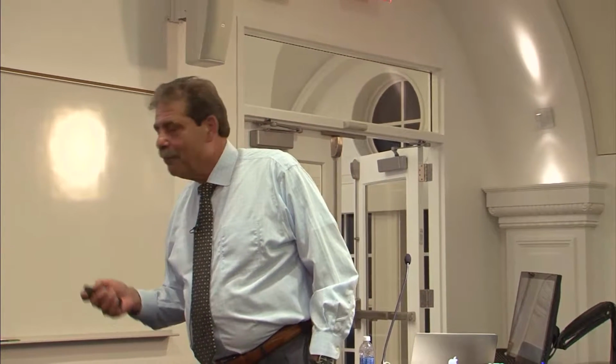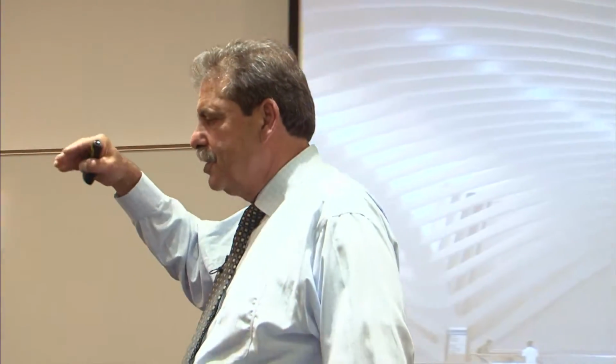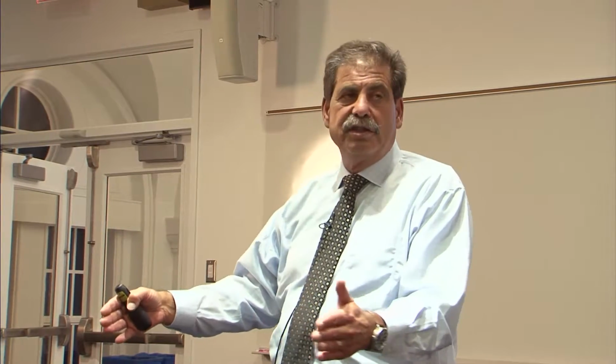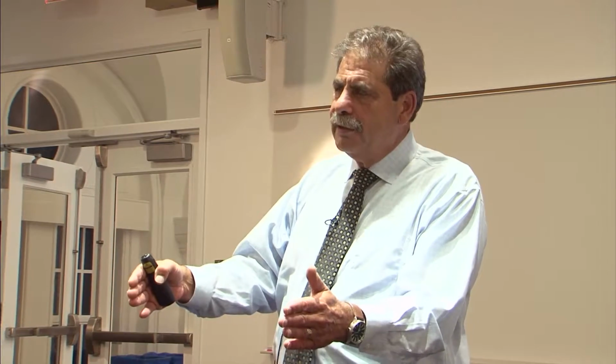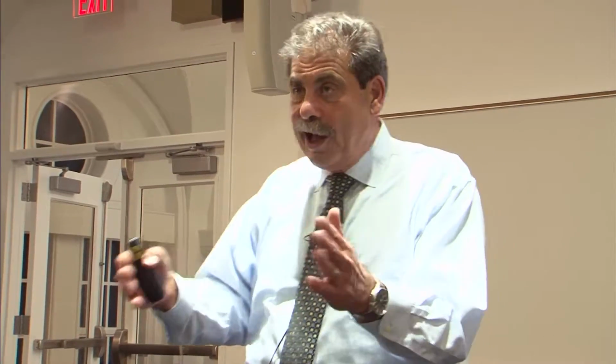This is what you can see. Now, here's an anecdote. Meetings with all the stakeholders. I can remember a meeting with Davis Brody Bond, who did the memorial, and it was Rod's design, but Davis Brody Bond was the executive architect. I can remember being in meetings with them and arguing about 5/8 of an inch. We want you to move this wall 5/8 of an inch. Well, wait a minute. That wall is 3 feet thick. It's made out of concrete, and the tolerance on that is 2 to 4 inches. So you really want that 5/8 of an inch? I'll give you the 5/8 of an inch, but in the end, you're really not going to have it anyway, because the tolerance of building that wall is such that it's going to be 3 inches into your space anyway.